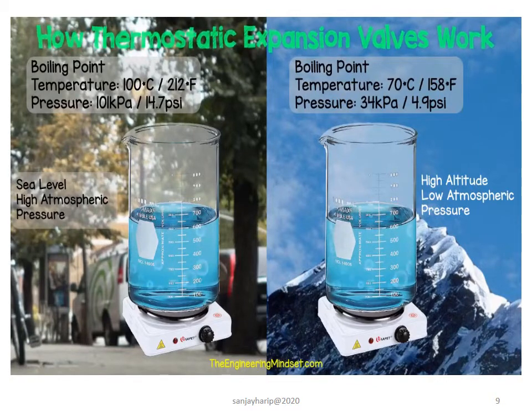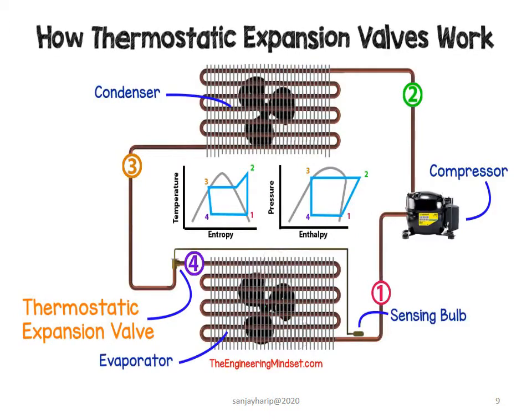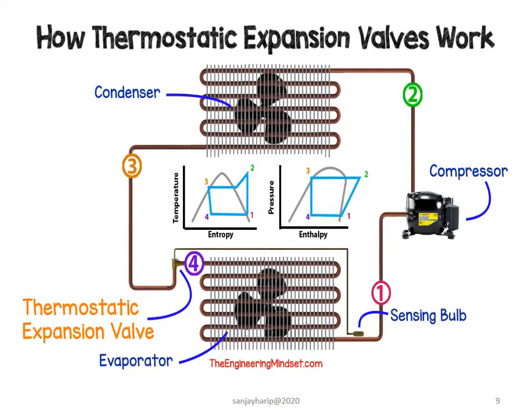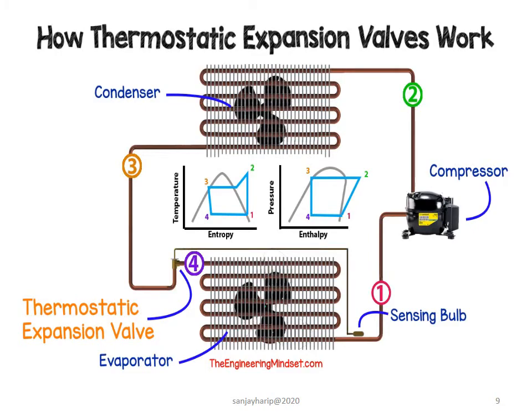And that's because we're higher up, so there's less atmosphere above us to push down on the water, which makes it easier to boil. The boiling is essential for the refrigeration system, as it will absorb the heat from the air or water and carry this away to the compressor. Also, just remember that the refrigerant has a much lower boiling point than water.